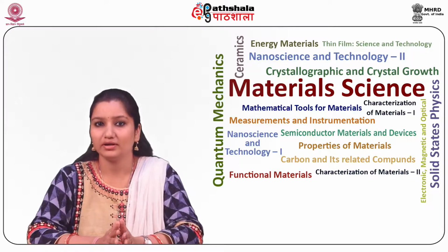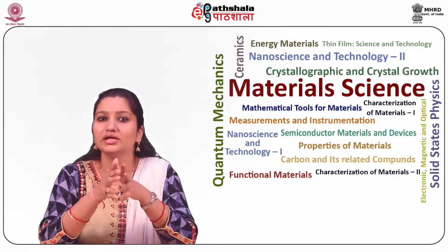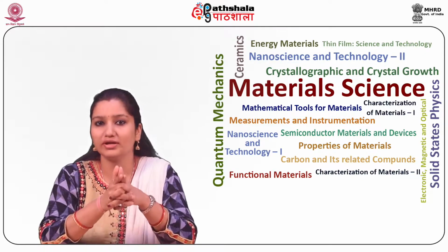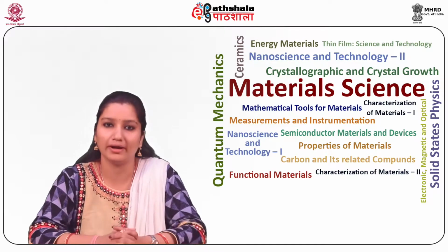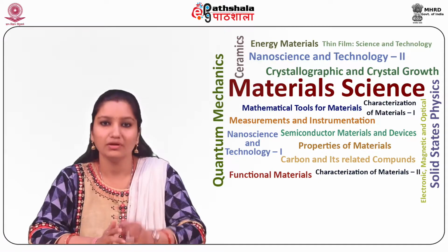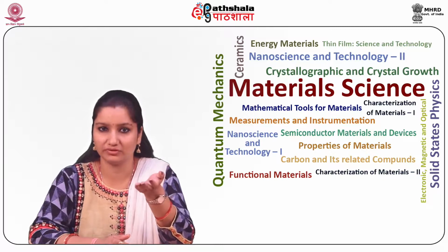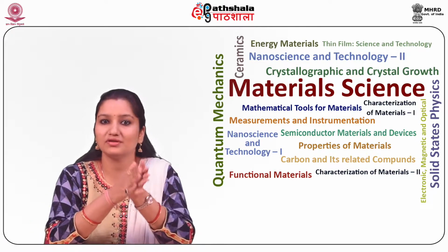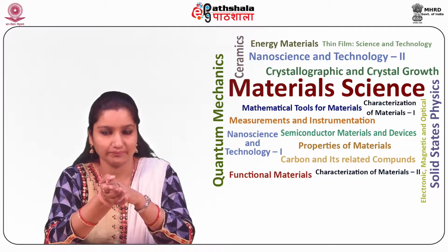The substrate placed at the grounded electrode is generally heated to 250 degrees Celsius to 350 degrees Celsius, depending on the film that needs to be deposited. In comparison, CVD, or chemical vapor deposition, requires 600 degrees Celsius to 800 degrees Celsius.